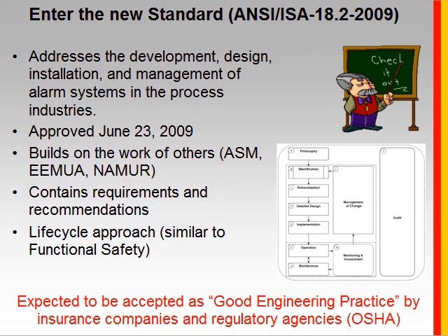It builds on the work of other recommendations from international sources, such as the EEMUA 191 guideline, ASM guidelines, the NAMUR guidelines. One of the major differences, though, between those sources I just mentioned and ISA 18.2 is that the ISA is a true standard.